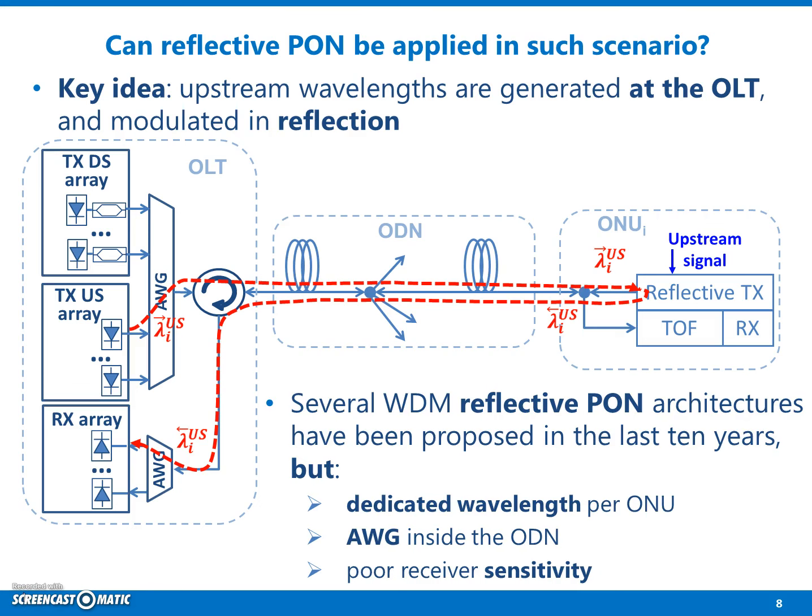Unfortunately, all the solutions proposed so far in literature are not fully compliant with next-generation PON requirements, in particular because their achievable ODN loss is usually well lower than the target defined by the standard due to several spurious effects, such as the Rayleigh backscattering and the very low received optical power.